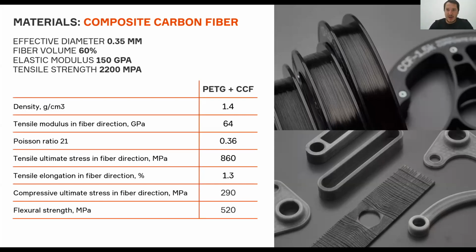Delamination can happen if the part is not properly designed and the part is loaded across the fiber, not along the fiber. Then, of course, it can delaminate and crack in certain cases. But yeah, it's not so easy to answer. It depends, of course, on the part and how you load it. I'm not sure if that was a good answer, but at least that's what I can say at a glance.